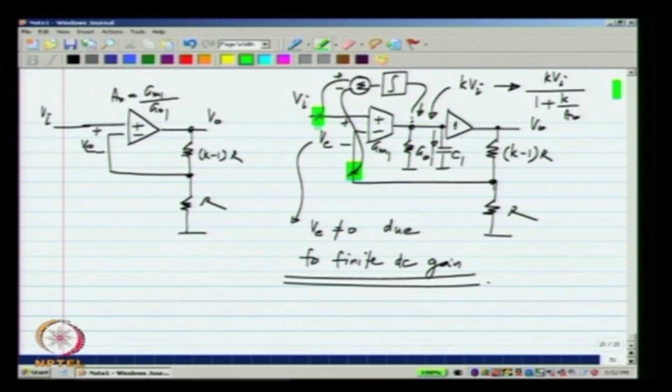So, what we will do is, we measure the error between these 2 points after it is settled, let us say, and then we integrate that error further and inject a current into this output conductance. So, once the current through the output conductance increases, this voltage goes up, this also goes up and the error will become smaller. It can even become 0 if this integrator is ideal, right. It is very clear, if this goes on integrating when the input is non-zero, the only way to reach steady state is when these two inputs are equal to each other or the input to the integrator is 0.